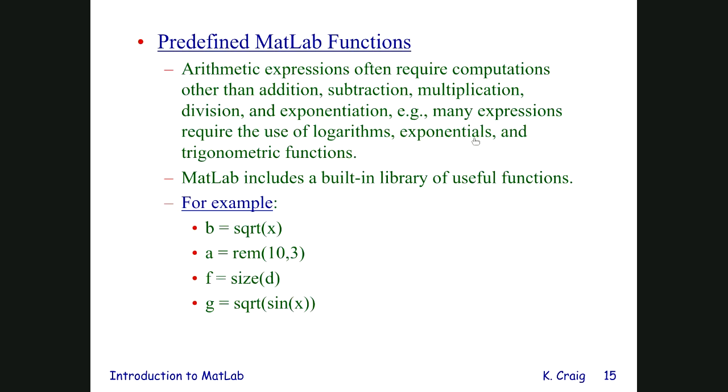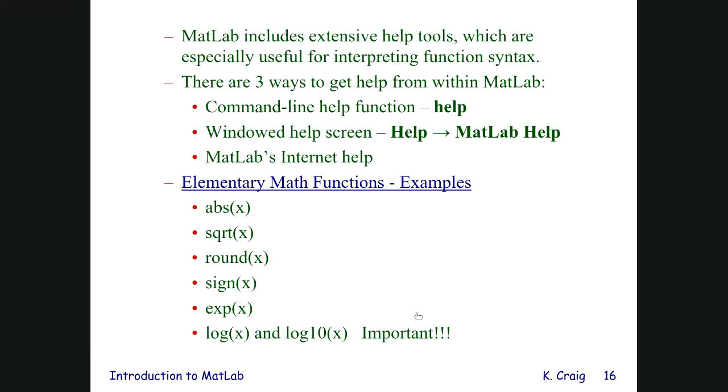There are lots of predefined functions, by the way. For example, taking square root, size of a matrix, sine, eigenvalues, eigenvectors, exponentiation, logarithm. This log is for ln, and log10 is for logarithm to base 10, by the way. You can use the help function to get help from MATLAB.